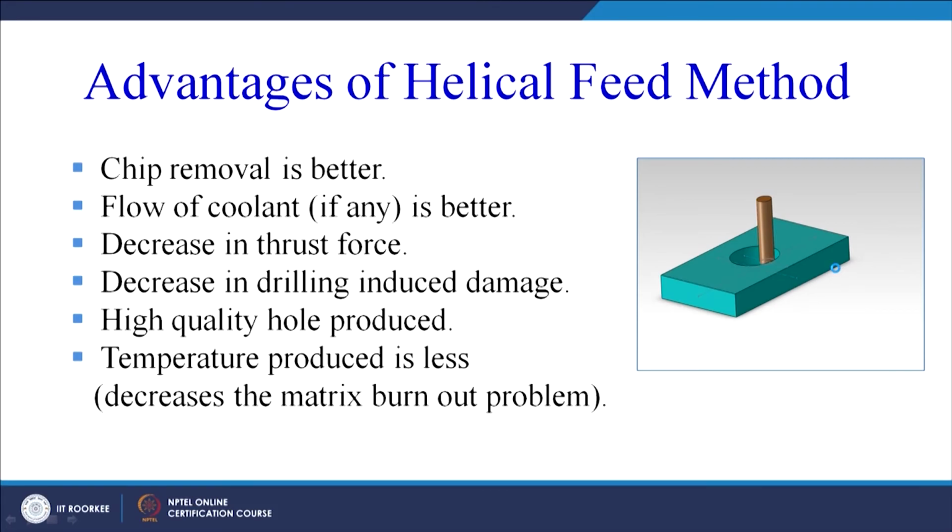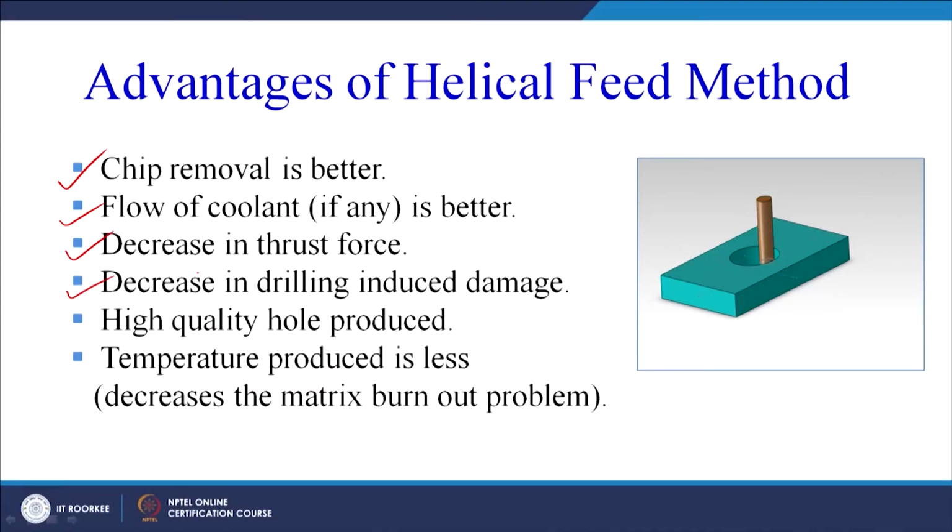Advantages of helical feed method: chip removal is better, flow of the coolant is better. Most of the time we have to take a decision whether the coolant has to be used or it can be avoided. Thrust force is less, decrease in the drilling induced damage, high quality of hole is produced, temperature produced is less, decrease the matrix burning out problem or matrix burnout problem. So, burnout can be put like this. So, it can avoid the matrix burnout problem also.